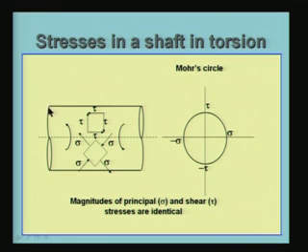So, imagine this shaft to be the shaft of the engine, which is driving either the generator or is connected to a brake. On the brake side, you need not measure anything. Now, I am measuring everything on the shaft itself. The advantage of this is that it can be permanently attached to the shaft, and you can do the measurement without any problem. It does not involve too much manipulation as in the other case, where you need an external measuring device, a force balance, and things like that.